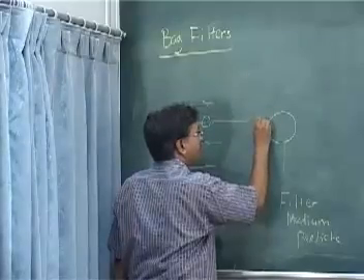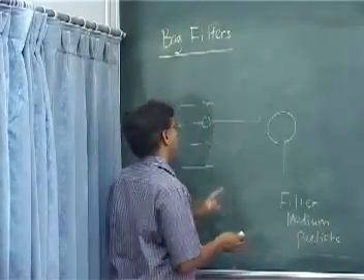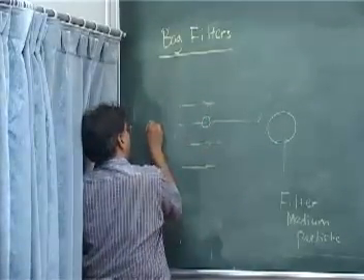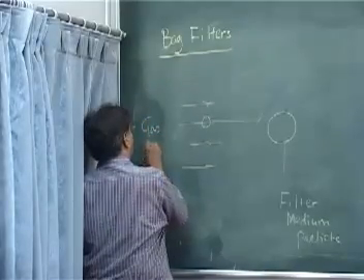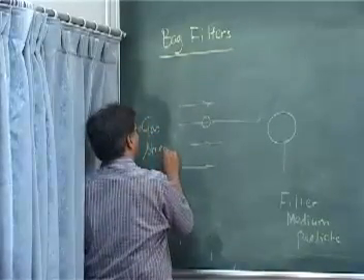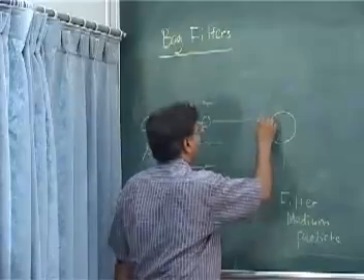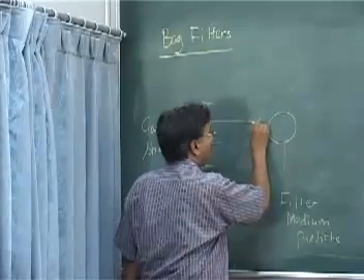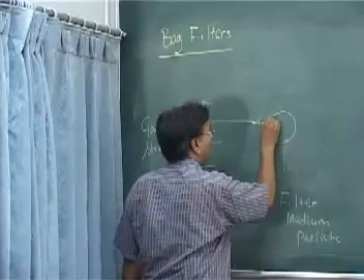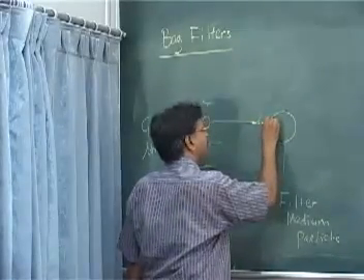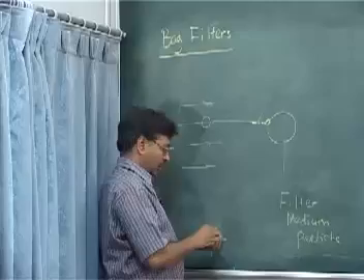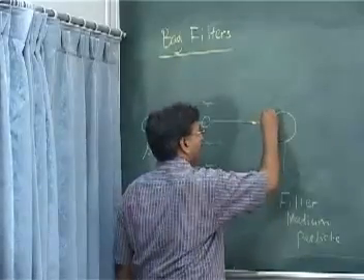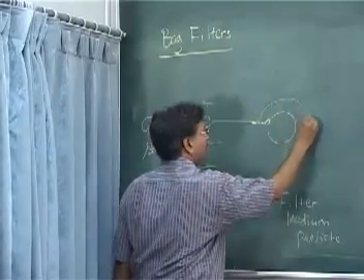The gas stream will change its path, okay, but this particle, because of its inertia, will leave the path of the gas and get stuck onto the fabric filter, and the clean air stream will continue to go like this.